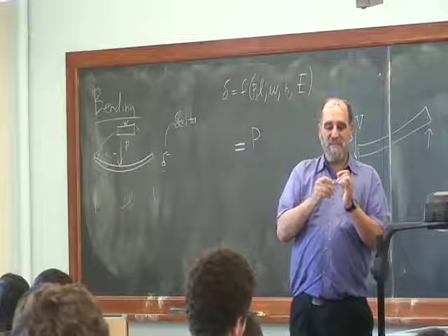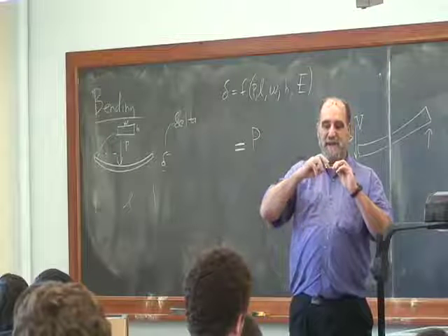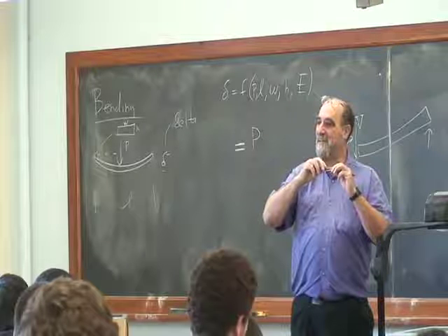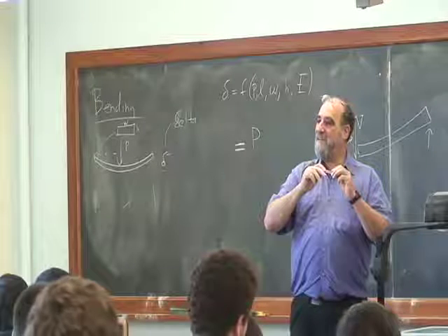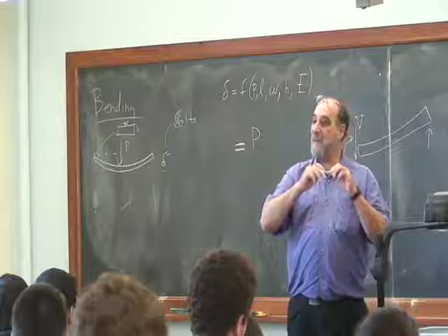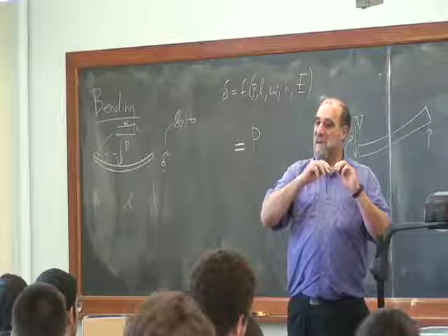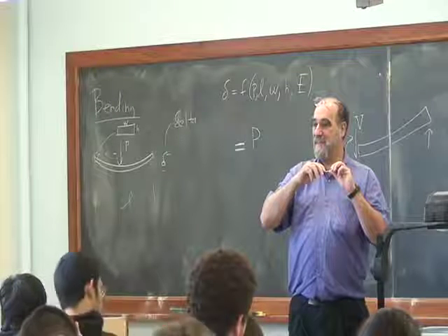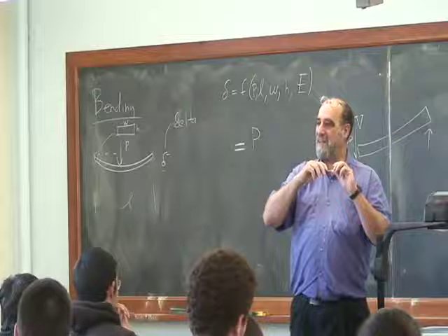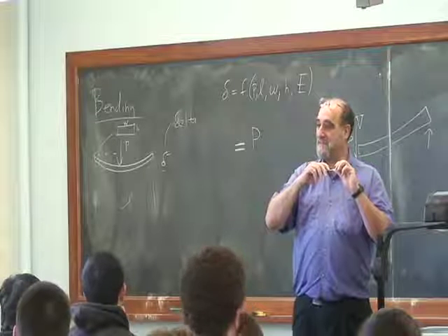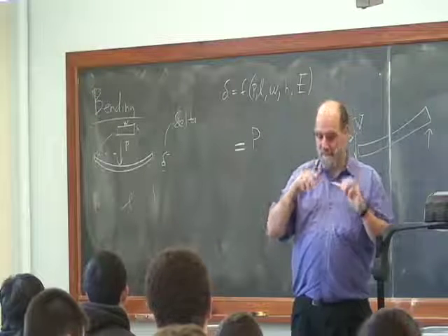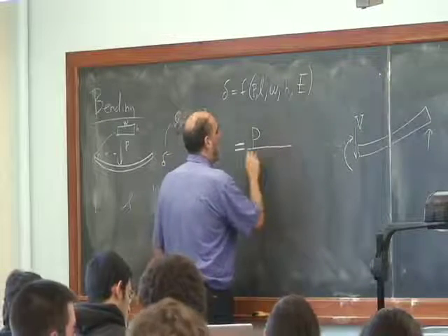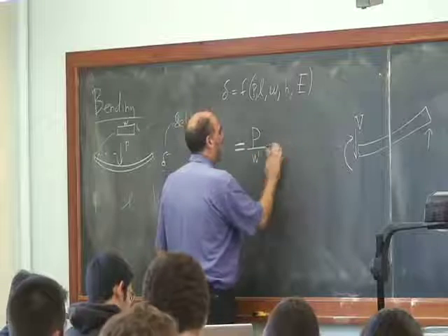If I put two of them side by side and apply half the load to each of them, I get half the deflection I got originally. But since I applied half the load to each of them, it's the same total load. Now they're side by side. I glue them to each other side by side. Nothing changes. So when I put two side by side, the deflection is half as big.